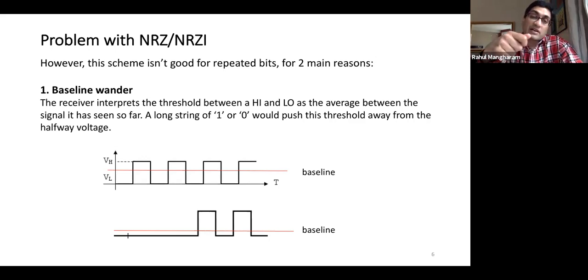So then the circuit would actually have to have a reset sort of mechanism in itself at every bit boundary. And implementing that reset kind of circuit to say, okay, well, so far I've got a 1, 1, 1, 1. If I have many zeros, then I do not have enough energy in the circuit. So the energy in the circuit basically is depleted in my capacitor to say this is what my baseline looks like. So then I'm just comparing, is it a 1 or a 0 to this baseline? And every time, the baseline keeps going lower and lower and lower because I have too many zeros at this point. And then anytime I have a transition, if the transition is above this baseline, I just treat it as a 1.